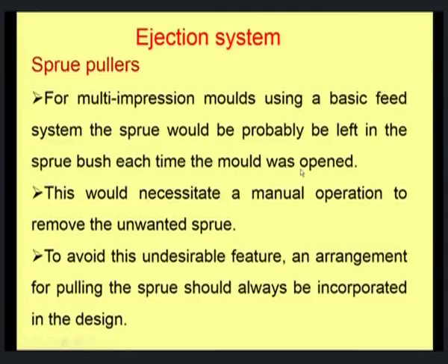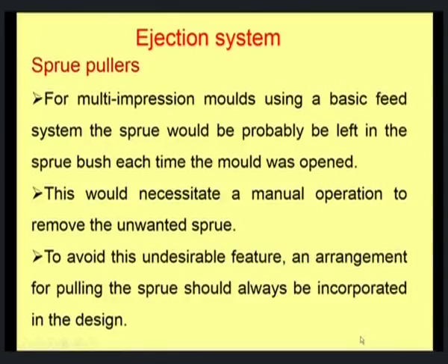So for a single impression system, the sprue is going to rest on the surface of the part. Therefore, as the part is ejected out, the sprue would also be ejected out, whereas in multi impression molds the sprue would be left in the sprue bush itself. So this will require a manual operation to remove this unwanted sprue for every molding cycle. To avoid this undesirable feature, an arrangement for pulling the sprue should always be incorporated in the design. That is what we mean by sprue pullers.